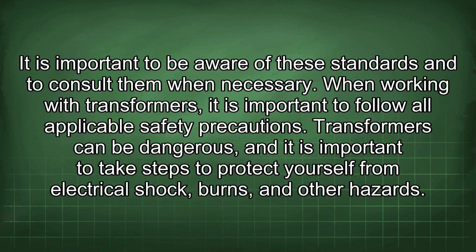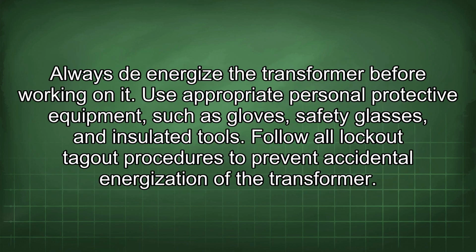When working with transformers, it is important to follow all applicable safety precautions. Transformers can be dangerous, and it is important to take steps to protect yourself from electrical shock, burns, and other hazards. Always de-energize the transformer before working on it. Use appropriate personal protective equipment, such as gloves, safety glasses, and insulated tools. Follow all lockout-tagout procedures to prevent accidental energization of the transformer.